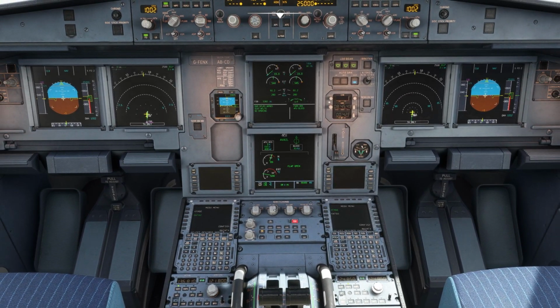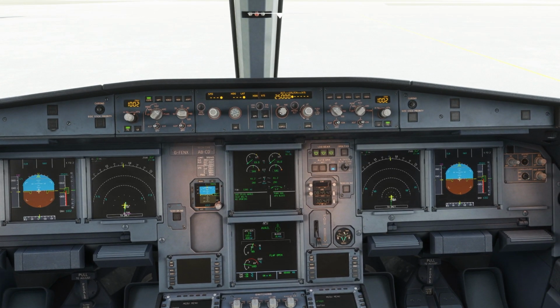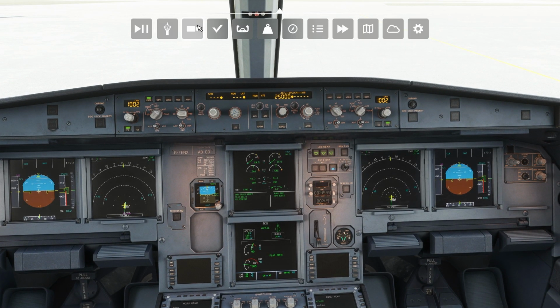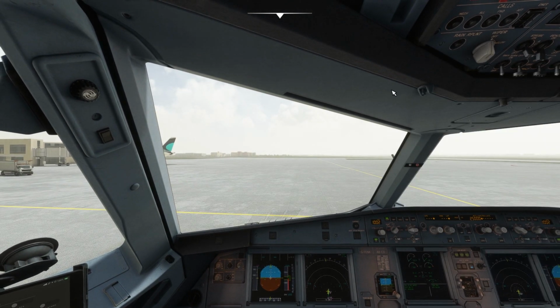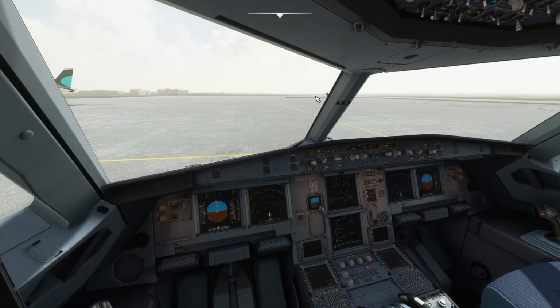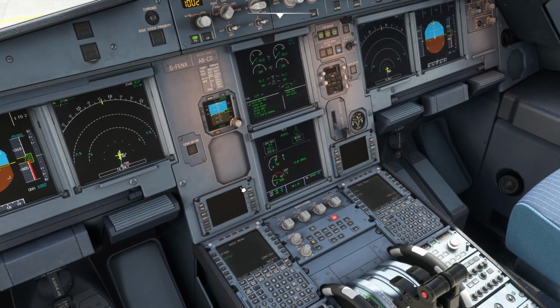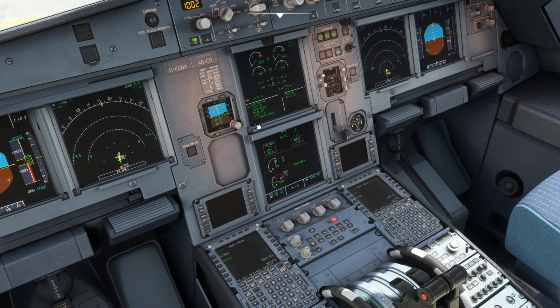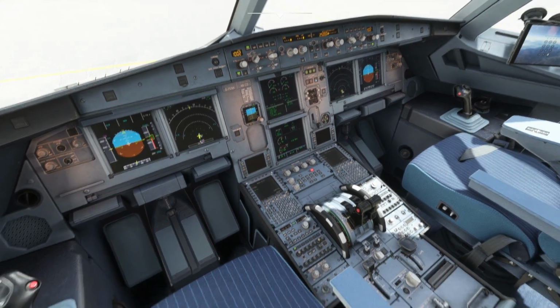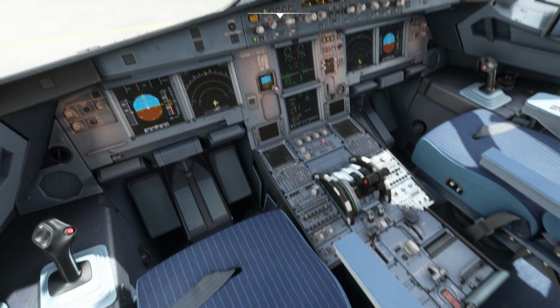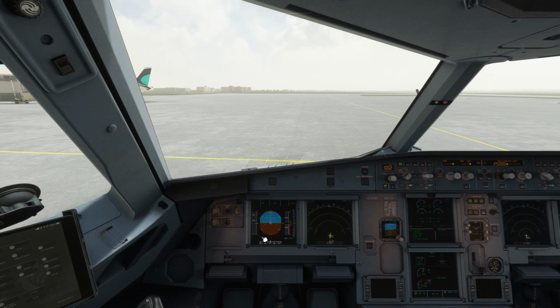We have entered all this information, the barometric pressure for the altitude. This is to basically adjust it, and it's good. That's it. I think I'm not missing anything, and I can just click this option, takeoff configuration, and you will see that everything is good. Auto brake set to max. You can see signs on, cabin ready, spoilers are on, armed, flaps set to takeoff, and takeoff configuration is normal. So it means everything that I've done is set. Now I can release the parking brakes and I can start the taxi.